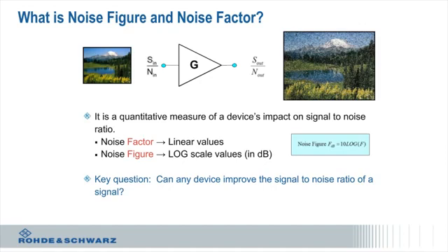So typically you'll hear noise factor, that's talking in linear terms, or noise figure, which is in dB scale. So typically RF microwave engineers talk in dBs. You might find, if you're new to this, when you first start playing around with dBs and you take 10 log of some ratio, you'll be going back and forth, but you actually find when you get good at it that you want to just live in the dB world.